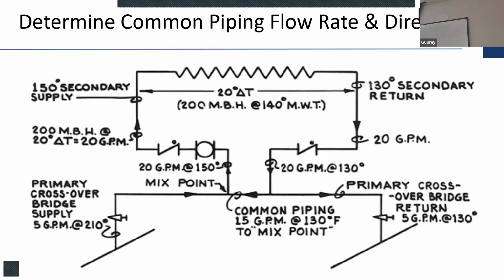Yes, sir. I'm sorry. In reality, no, no. Well, you could use, but that three-way valve would be here, one of these two. Well, but if it's up here, then it's never going to see that pressure drop. Unless you connect it. I know where you're going. They would use that three-way valve, the CV of the three-way valve, as pressure drop for balancing to get that 5 gallons a minute across.